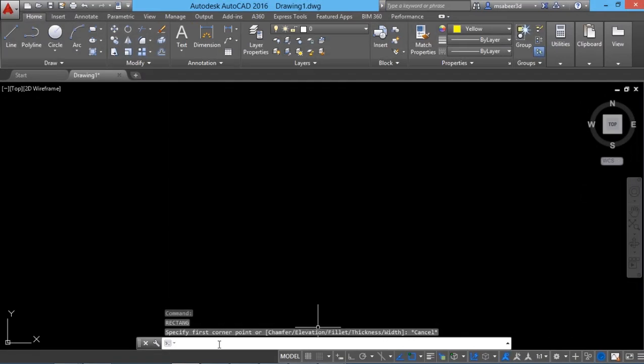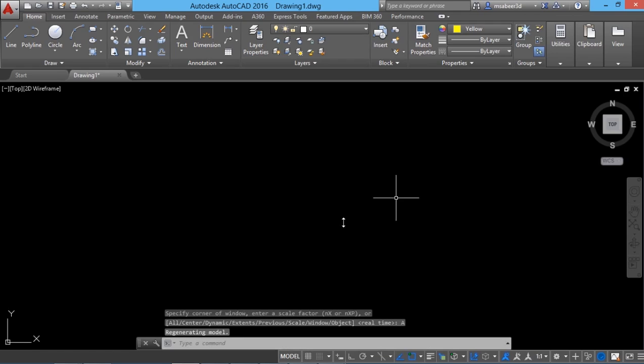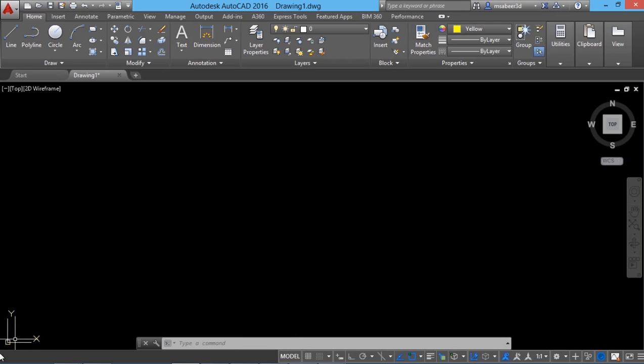So let's give the limits command in AutoCAD to get these limits on the screen. I'll give limits, and for the lower left, when I'm asked, I'll give minus 60, minus 60. And for the upper right, when I'm asked, I'll give 60, 60, followed by Z for zoom, and I'll type the letter A, or I'll click on all to get the limits on the screen. Obviously, all the 4 quadrants are in the screen, but the origin still remains here.